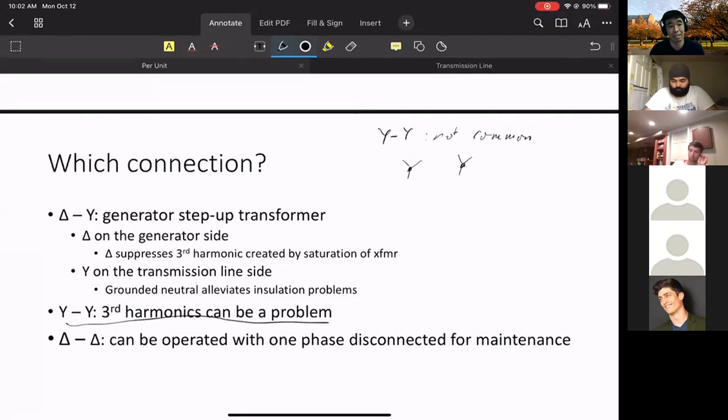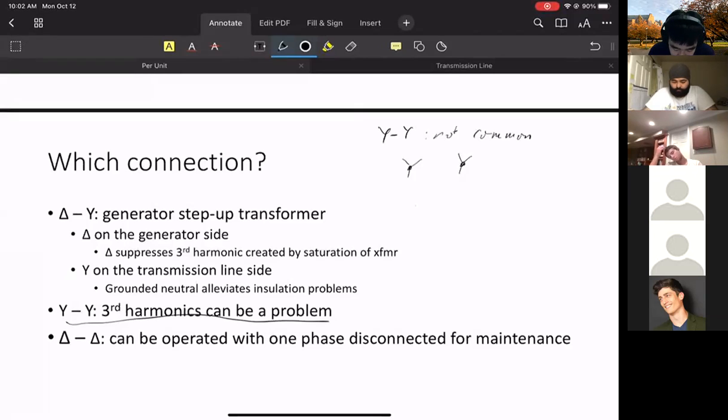and the voltage magnitudes are exactly the same. So if the three phases are not exactly the same, then this thing in the middle is not zero. You basically have three slightly different sinusoids adding to each other, and this causes something called higher order harmonics.